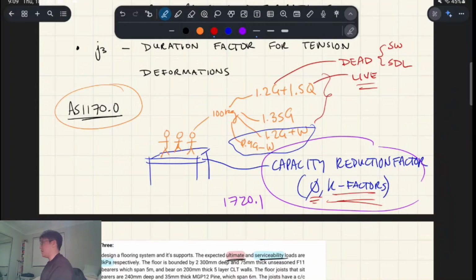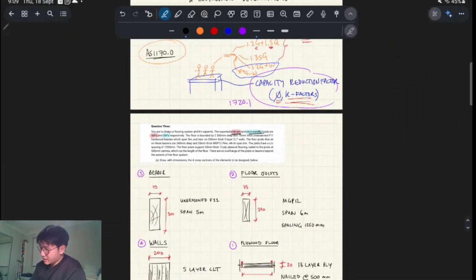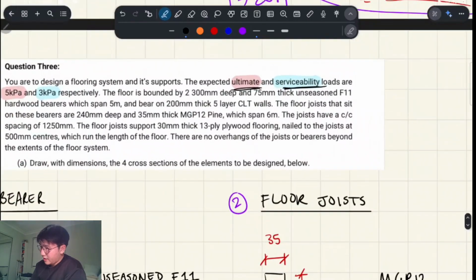Vehicles, yeah, those are all live loads basically. Because you don't know as much about live loads, they're more variable, you have to exaggerate them more. So that's why there's a 50% increasing factor for live loads, whereas dead loads are more consistent, and so we only have a 20% increasing factor. Okay, cool. Does that make sense? Yes, it does. Okay.